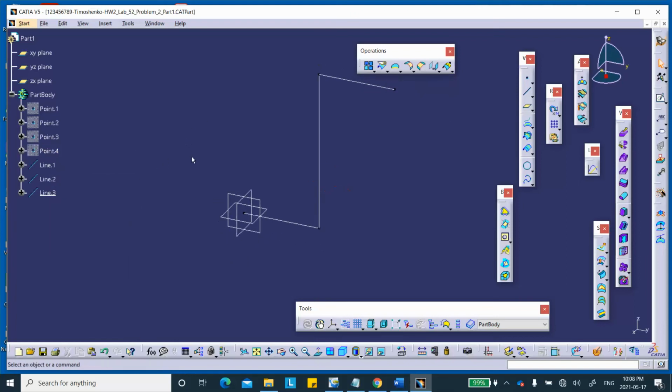Okay, very good. The other thing is I join these, because if you don't join it, when you mesh it, it'll mesh this, but there will be a node number on this side which is going to be different. When you mesh this, it's going to have a different number.